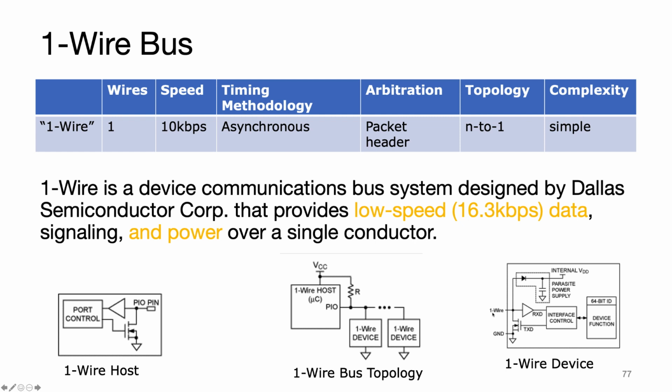And what's interesting is that the one wire comes in through a voltage harvester. So if nothing's going on, current is going to go through here and charge up this capacitor through this diode. Remember, a diode is like a one-way valve. So if the voltage here is 0.3 volts higher than the voltage here, current will flow and charge this up.